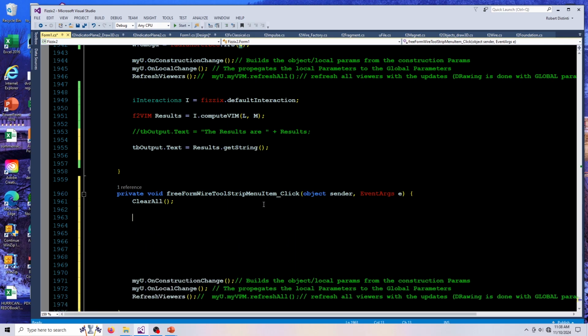So what we're going to do is we're going to do everything in centimeters now. Okay, we're going to define a straight segment length. We're going to use a default centimeter. Okay, just so you know, in this little meters thing, you can specify AWG, which will give you the diameters of, let's say, a 30 gauge wire. And that's how, when I specify default of something is 30 gauge, it's in meters, but it comes from this thing here. Okay, but we just want centimeters, a little segment there, and then we're going to have a diameter.